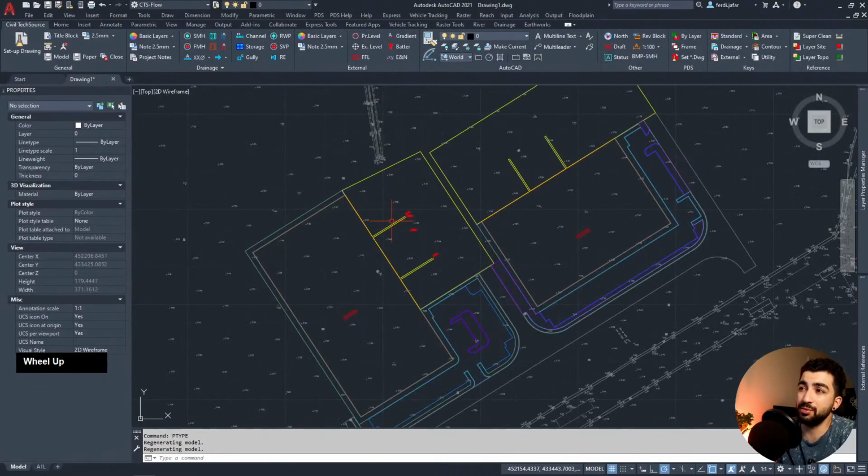Now what I usually do is, before I close my drawing, I always bring it back to world, and the reason I do this is so that my colleagues, when they're not aware of the UCS, or if they don't clock that the UCS was not set to the right coordinates, when they XREF and change drawings, it will come in the right place, and they won't be like, huh, why did it end up there? So always have a safe practice.